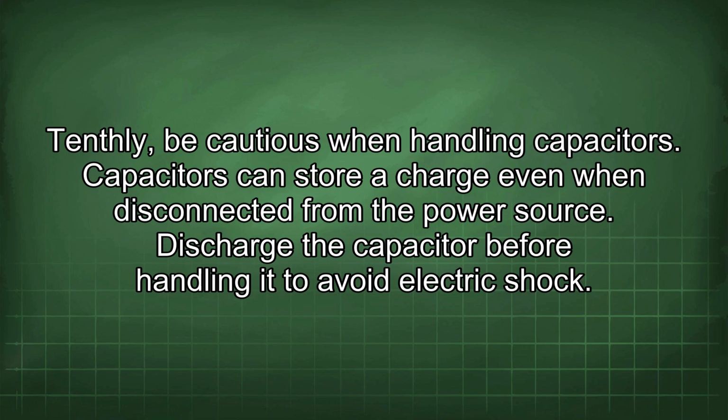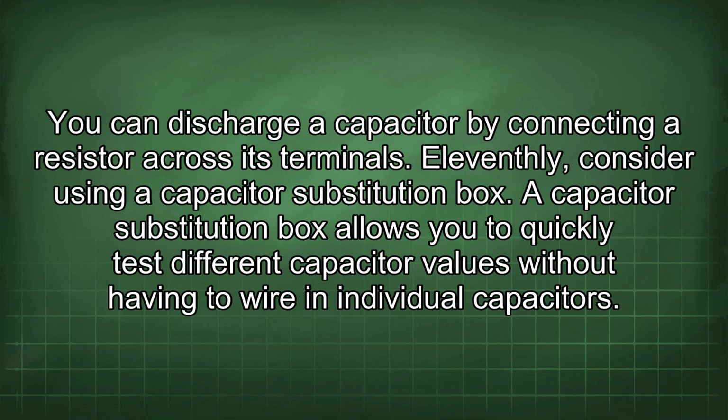Tenthly, be cautious when handling capacitors. Capacitors can store a charge even when disconnected from the power source. Discharge the capacitor before handling it to avoid electric shock. You can discharge a capacitor by connecting a resistor across its terminals.